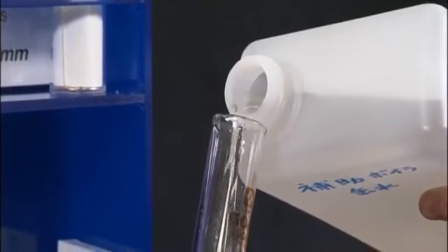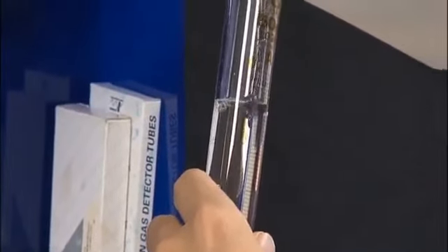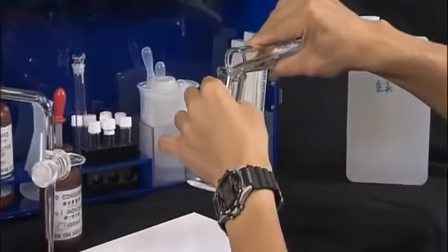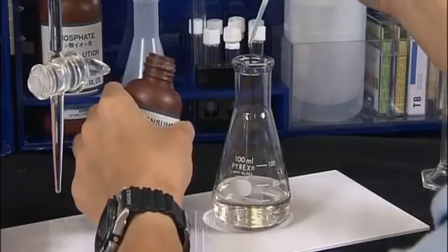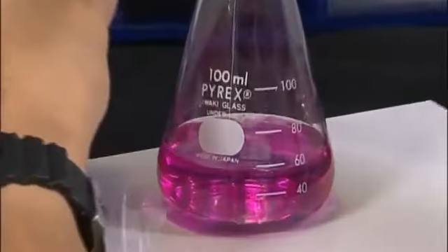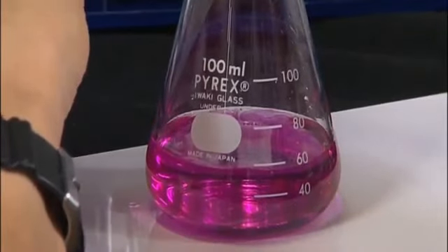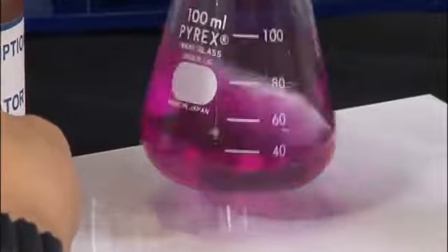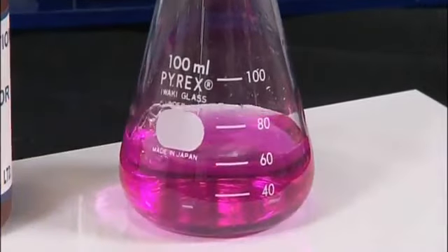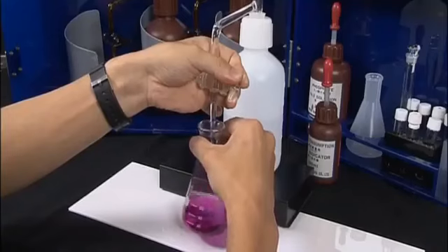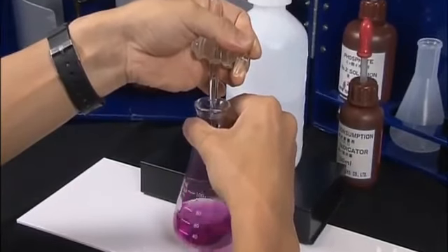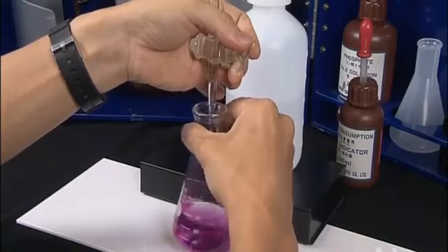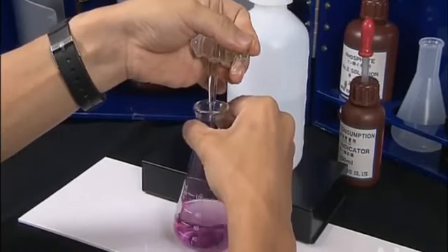Here is an example of p-alkalinity measurement. Put an adequate amount of sample water into a beaker and add 3 drops of phenolphthalein indicator. The sample water will turn pink. Next, determine the amount of sulfuric acid consumption by titrating 1/50th prescribed sulfuric acid into the sample water until the pink color disappears.